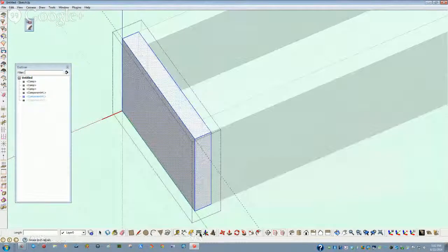Now, with the protractor tool, you can pick that existing element by picking a pivot point and then a lever, and down in the corner where it says angle, you can enter 45 here, or you can just drag it until it defaults to it. Hit the space bar to release everything.